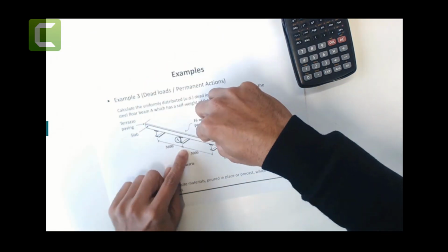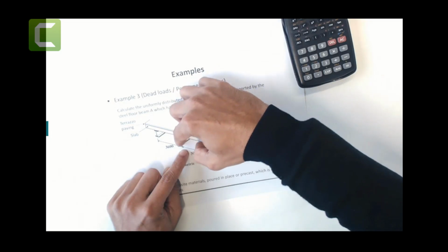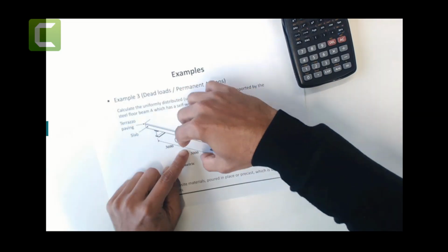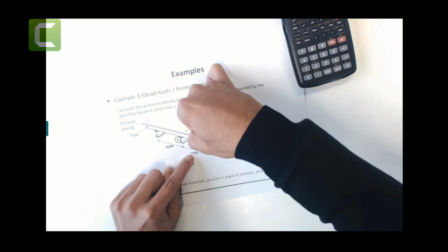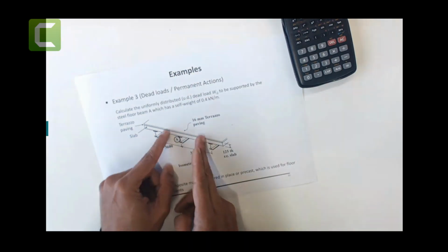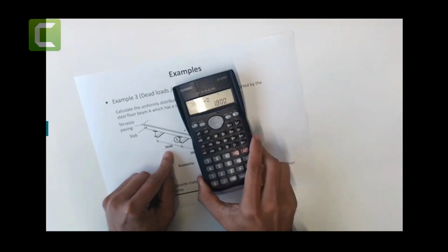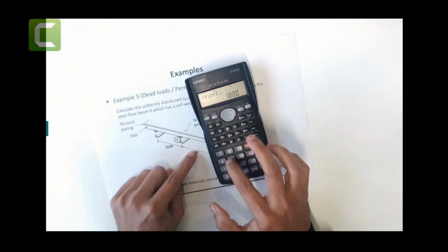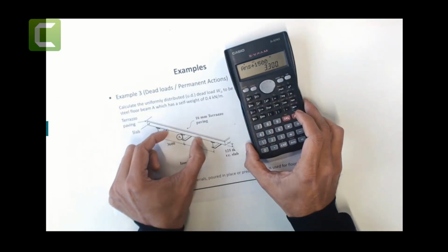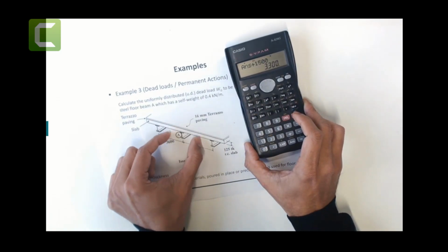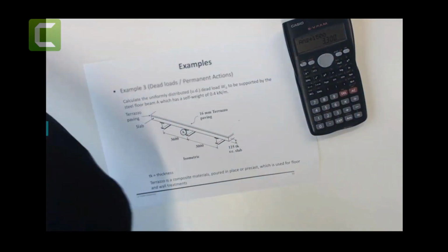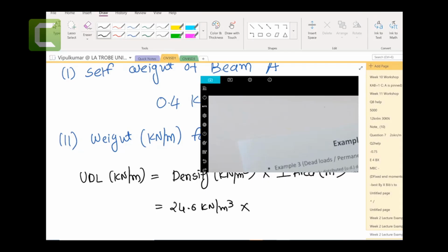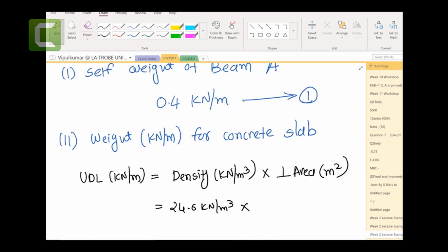And if I come this side, these beams are going to share the weight from this beam to this beam. So it will get 1500 here. So this guy will have 1800 plus 1500. It gets 3300, 3.3 meters. It is going to be carried by these beams. I can explain this one. Just keep in mind these figures. Let me draw up the pictures.